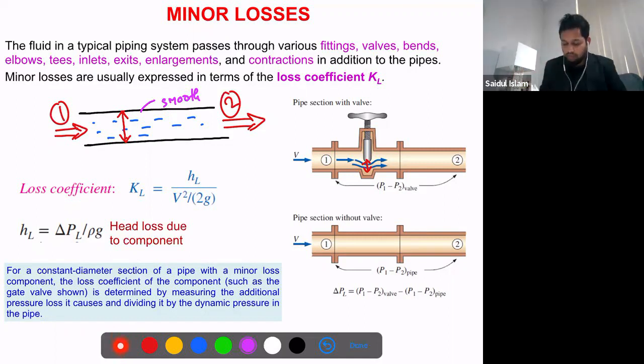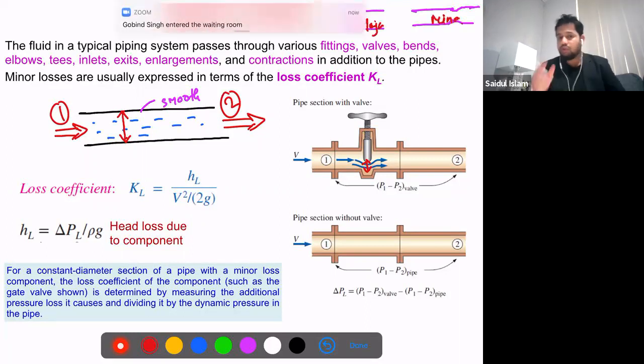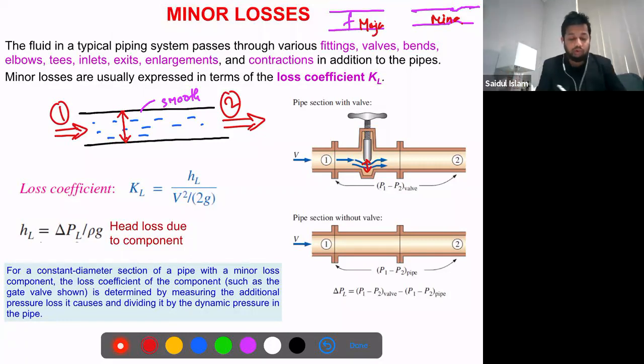My conclusion is, now I will show you two things. We have one pipe where we have the friction loss, and another pipe, let's say, with a stenosis section like this. For this pipe we have the major loss. Here we have minor loss. I'm just talking about when we have all this: fittings, valves, or any of these arrangements or inserts. This minor loss, in some cases, could be more significant than the major loss.